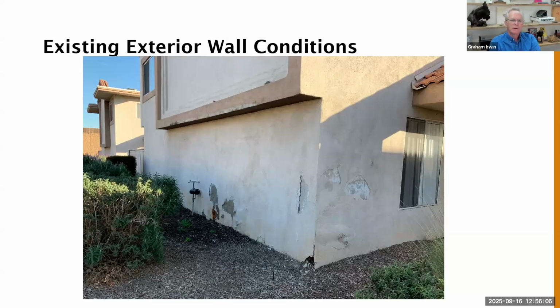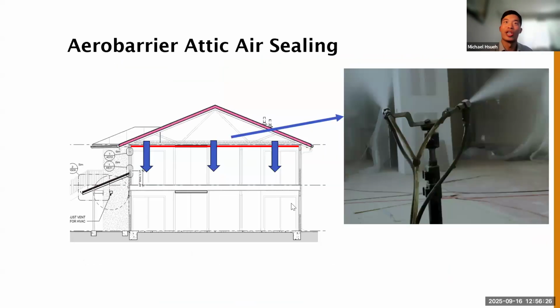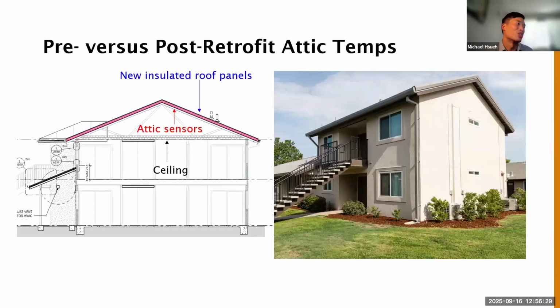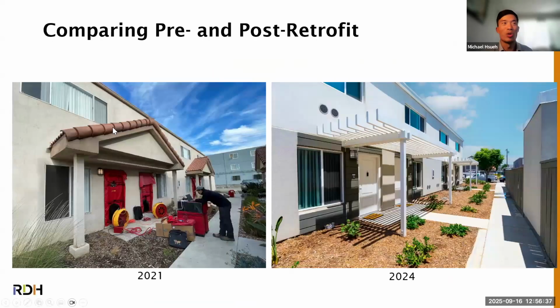I had a question. Sure. Was the air leakage through the replacement windows given any consideration? So what we did for this building specifically was we did measure air leakage through the windows, because we did a whole building air leakage test. It's just a photo of me doing blower doors, but basically we installed 4 blower doors. Yeah, here we go. This is me running a whole building test. All of these 4 units are connected. I installed blower doors in all 4 and controlled them, pressurized them to the same degree, so that we are including air leakage through the windows.